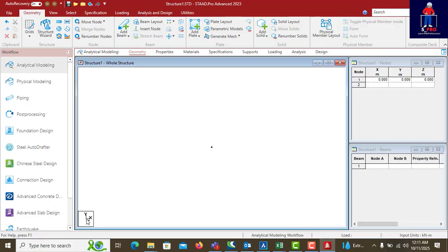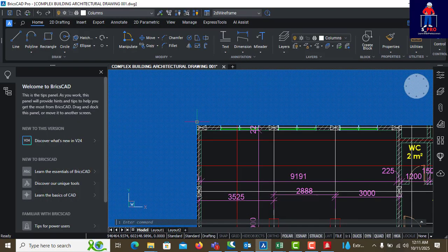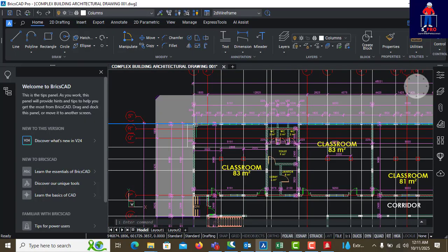Okay, so if you look at our coordinate system, you see that the vertical axis is y, positive y pointing upward, x is going to the right while z is coming to this axis. So you have to now choose a perfect place for you. Me, I don't like having negatives in my coordinates. Because of that, when I go to the plan, I choose this point. So if I'm coming down, it is positive z.